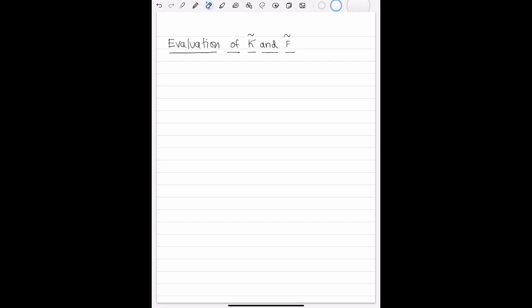So in one of our previous lectures, we discretized the weak form, and using that we generated a system of equations, or a matrix equation, given by KD equal to F. Here K is our stiffness matrix, F is the forcing vector, and D is our unknown solution vector which we need to solve for. So in today's lecture, we are going to discuss how to evaluate the stiffness matrix and the forcing vector now that we know what the basis functions are for the linear finite element method.